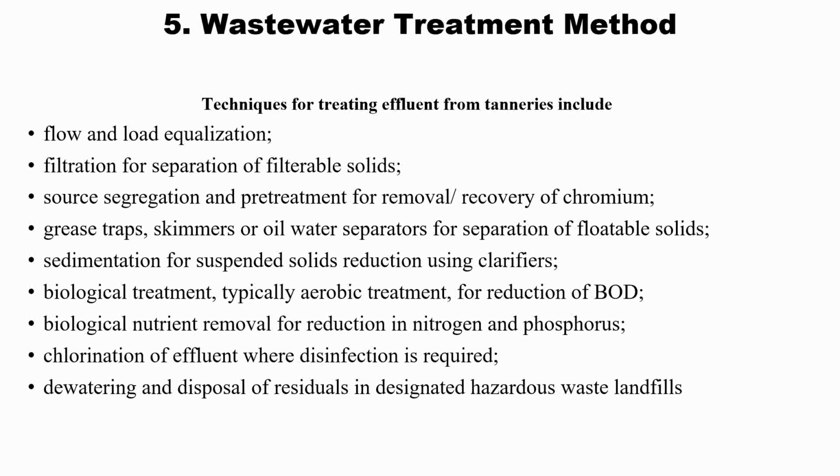And then it is followed by sedimentation, then biological treatment, and biological nutrient removal for reduction in nitrogen and phosphorus, then chlorination for the disinfection process also, because more organic matter is present, so it may lead to the spread of some microbial diseases. So disinfection needs to be done, and dewatering and disposal of the residuals in the designated hazardous waste landfill, or we can spend much more time and money to treat the water.